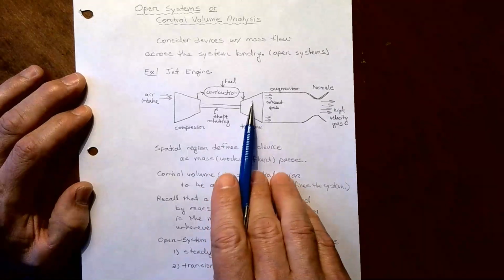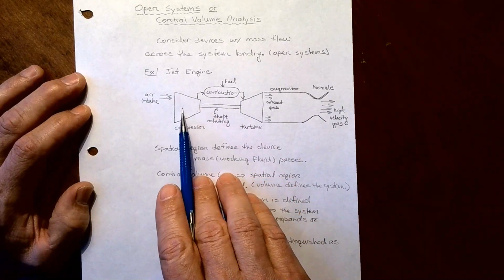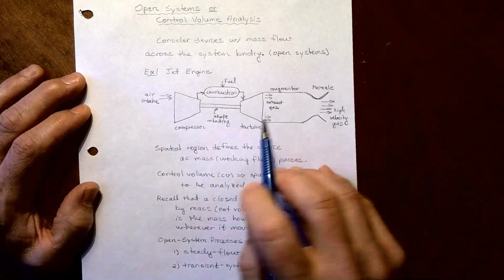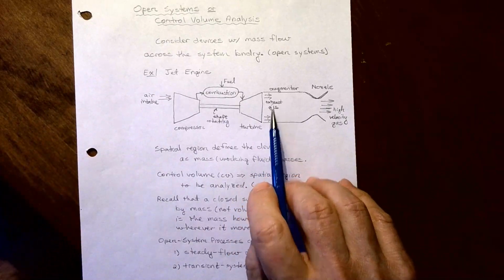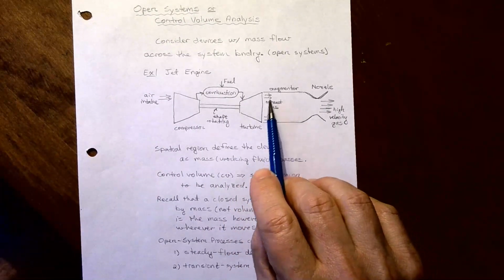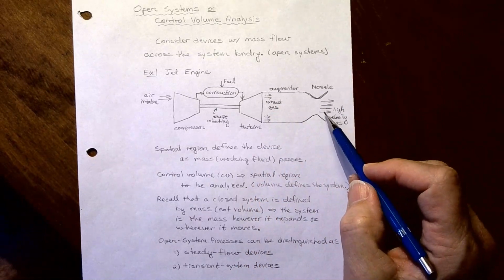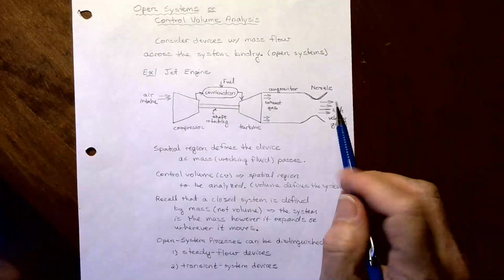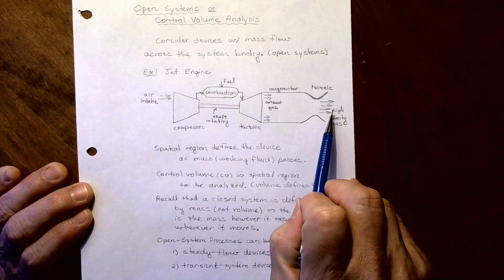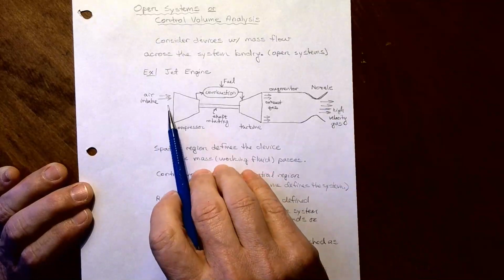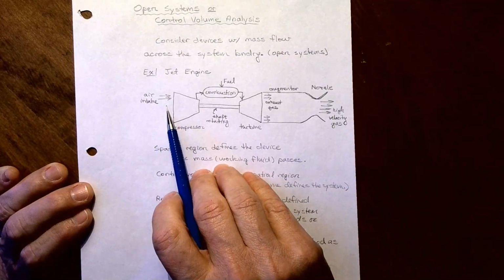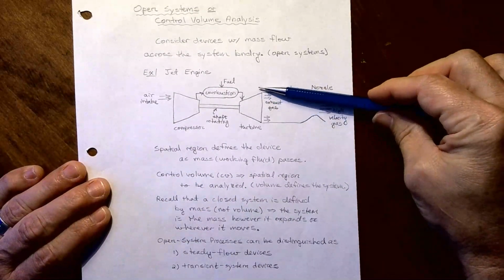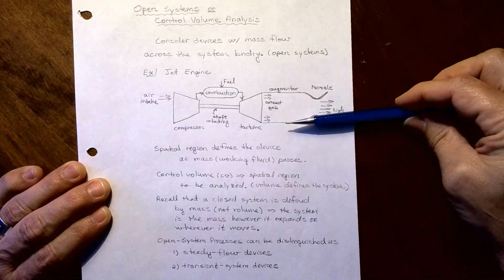Some of the energy is taken out of that gas through the shaft power required to drive the compressor, so this is an internal rotating shaft. The rest of that gas enters an augmenter, basically an open pipe, and is nozzled out the back. A low density, high velocity gas is nozzled out the back, causing thrust. The velocity of the exit gas is much higher than the velocity of the intake gas, providing a net thrust.